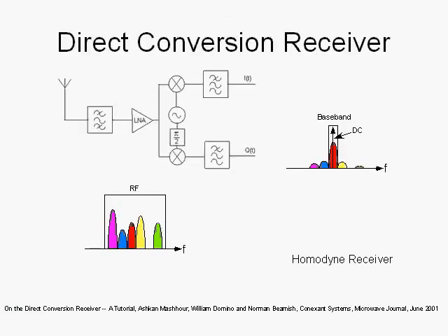We will discuss in detail the direct conversion receiver, in which we take the channel of interest and demodulate that back to baseband. That, of course, has many advantages and disadvantages, which we'll go over all of them in detail. In particular, with direct conversion receivers, we have issues in terms of DC offset, in terms of IQ imbalance, and other issues that we'll deal with.